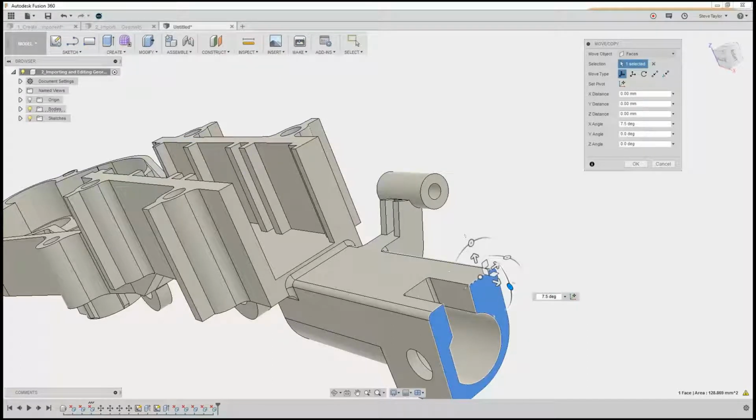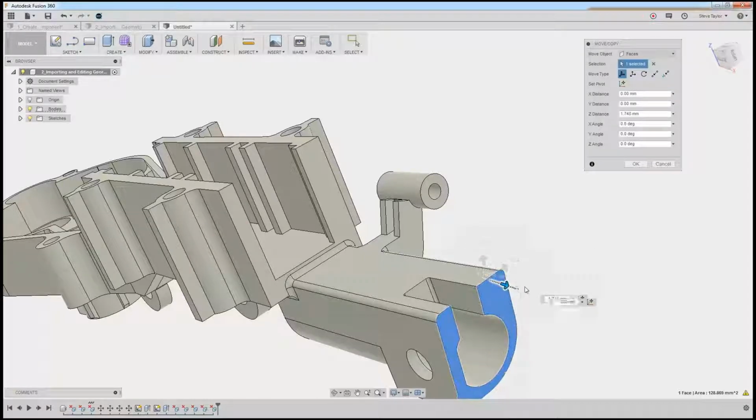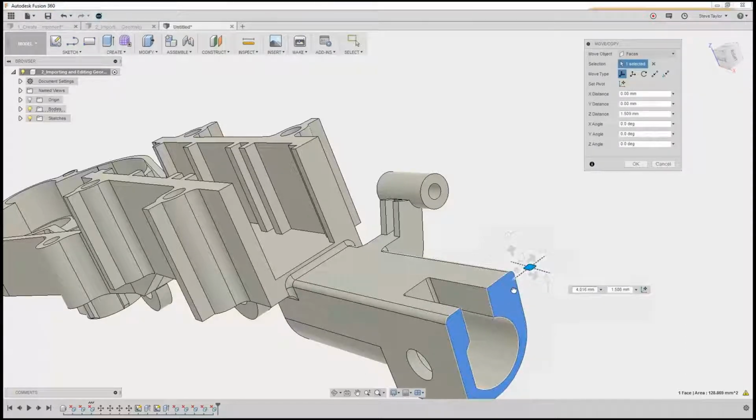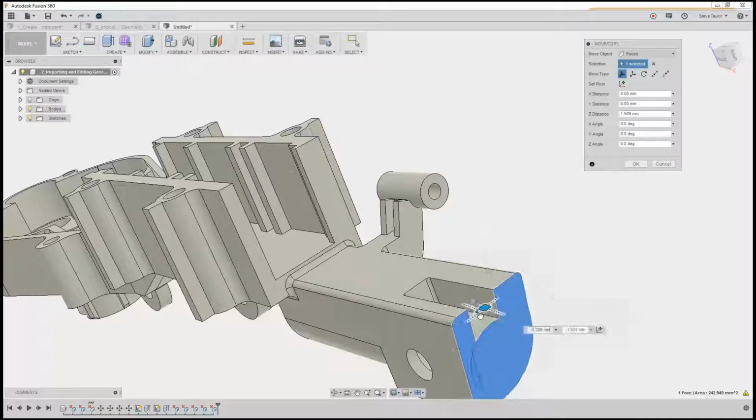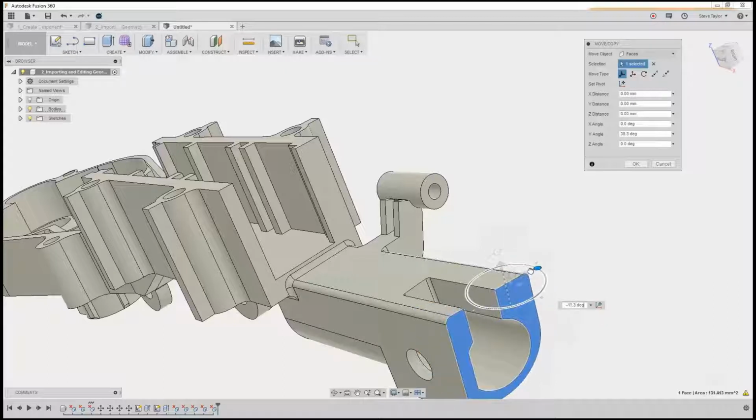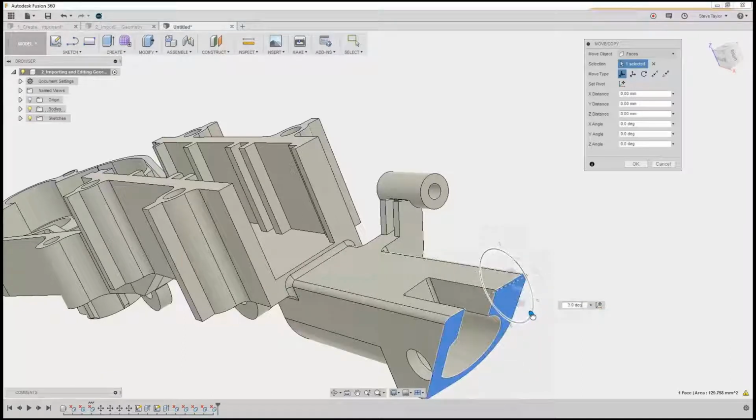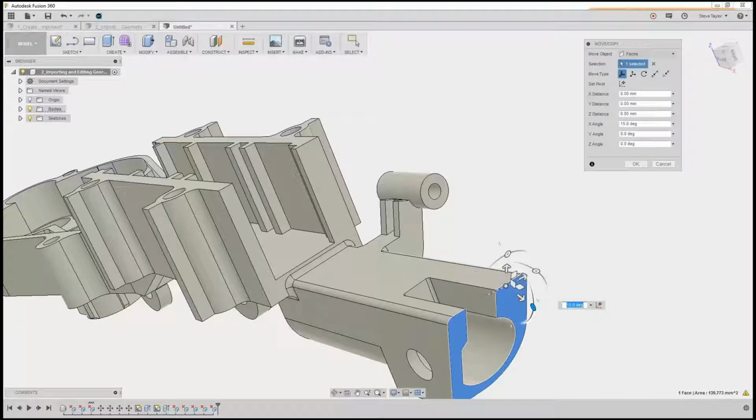You can simply just grab it, move it. It's just another way of working with it from there. I could pull it from there using that move and copy tool. I can do planar, but because of the particular type of geometry, you can see what's happening. If I'm not careful, I'm filling in that hole. So different pickups, that's not doing anything to it. It's one of these, you play about with it and see how it affects the actual model itself. You see that it's pretty good for rotating in certain directions. You can get a very quick and complicated model and design easily and rapidly.